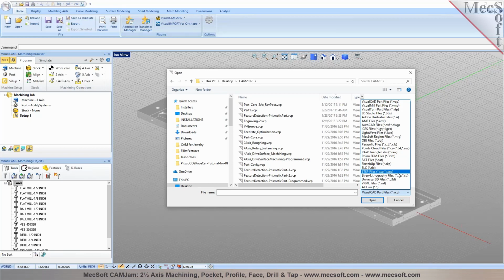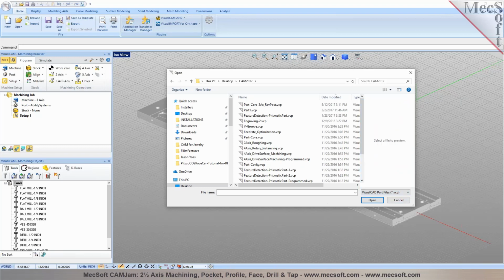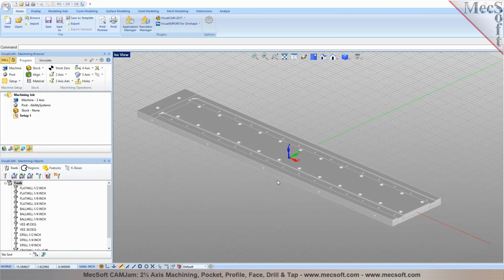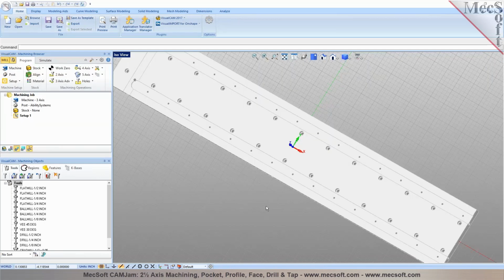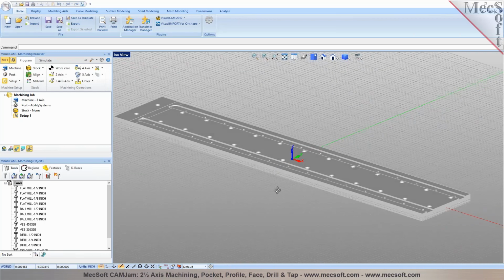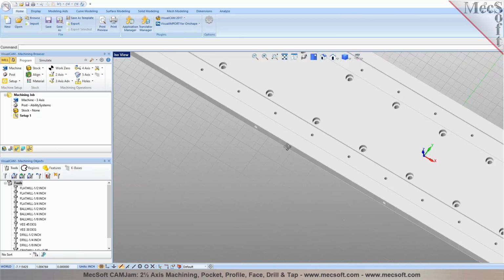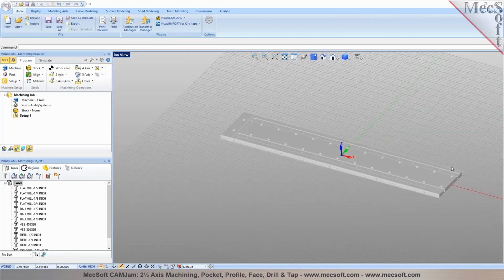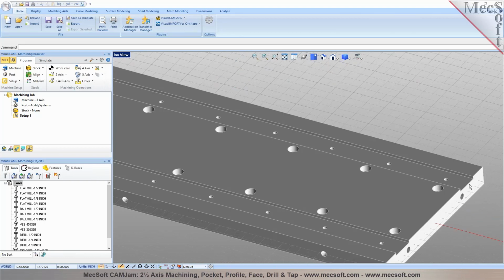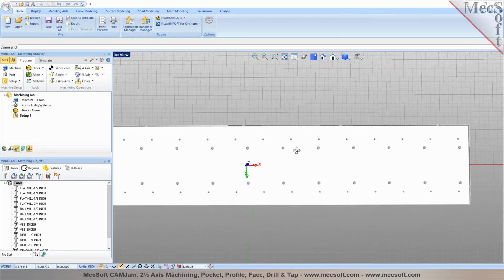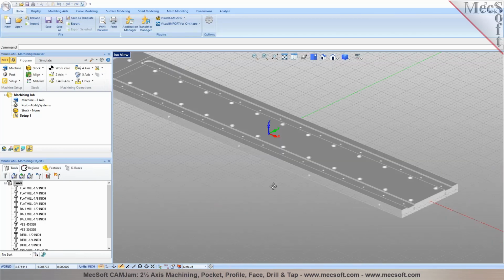Now, since you already had the file saved as a VCP and emailed to us, I just loaded the part directly into VisualCAD CAM. Right. I created that out from a step. It's kind of a multi-step process for me because I have to save my native files as a step, and then I can turn the step into a VCP. That is correct. So you can bring it in, open a step file, and then just save it out as a VCP. And when you add CAM information, the machining operations, they're all saved in the same file format, the VCP format. So it gets added to it.